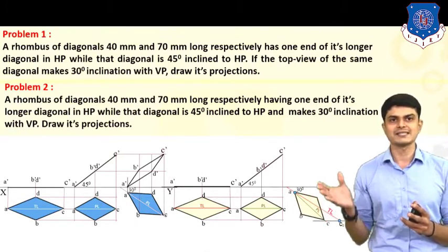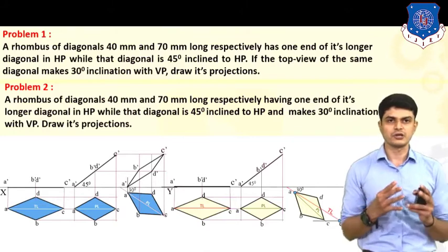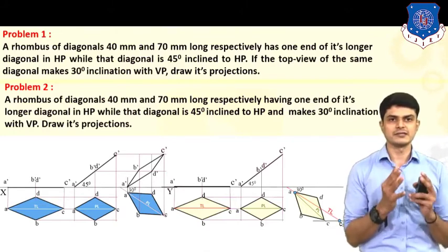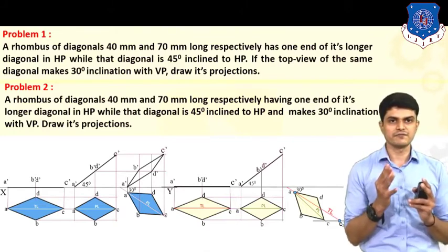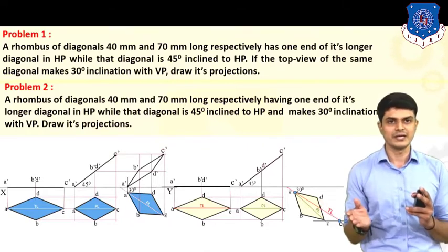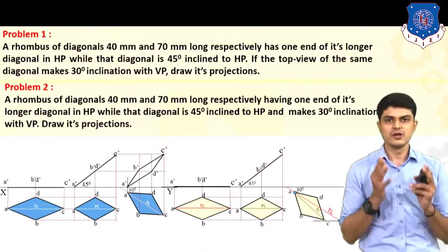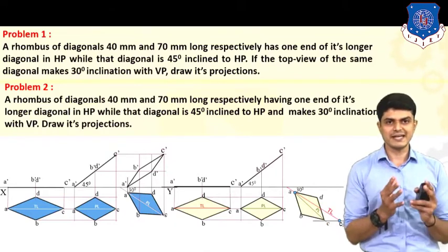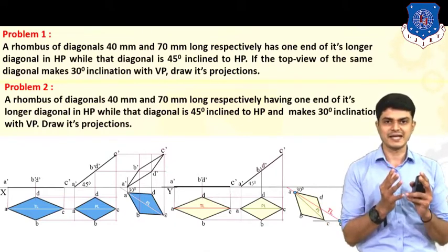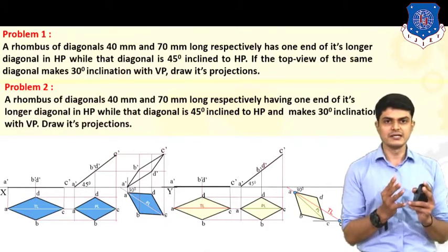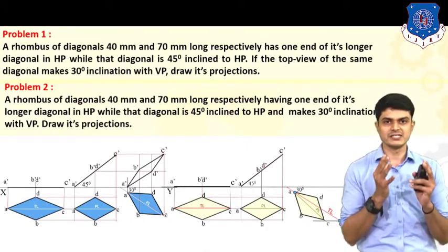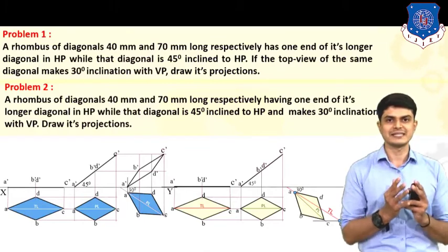After that, you just mark this point. So this is nothing but your final object in the third step. So remember the difference here: we have taken the angle with the true length and then we have plotted the plan length, and based on the plan length we have drawn our object. So this method is also known as the plan length method or beta angle method. It is the most important method which is always asked in examination.